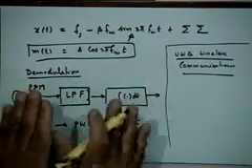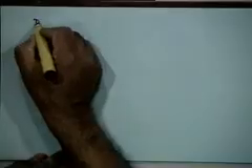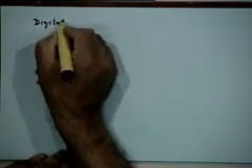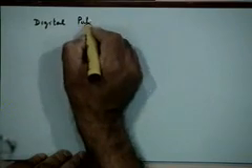But remember, what we have discussed is analog modulations. We discussed analog modulation of sinusoidal carriers earlier, and we discussed analog modulation of pulse carriers here. Right? Why analog? Because the message amplitude is embedded in some parameter of the carrier, which is again analog in nature, with its width or height or position. Right? Now, as against analog modulations, we can do this embedding also digitally. So you can also have digital pulse modulations.